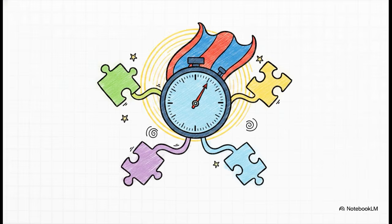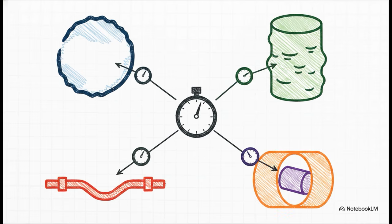Now, I want to let you in on a little secret. Total runout is often misunderstood, but it is actually a 4-in-1 tolerance superpower. When you drop a total runout symbol onto a drawing, you are secretly doing the heavy lifting of 4 completely different error controls simultaneously. Let's break down exactly what errors this single symbol is hunting down for you. According to section 12.4.2 of the ASME standard, total runout provides cumulative control of 4 variations. First, circularity.